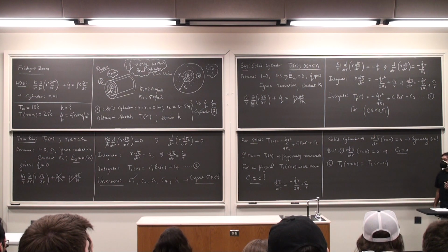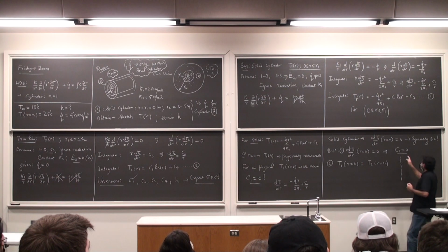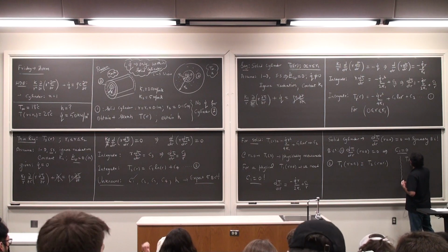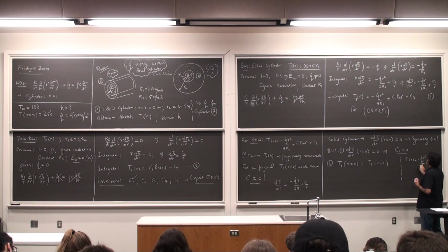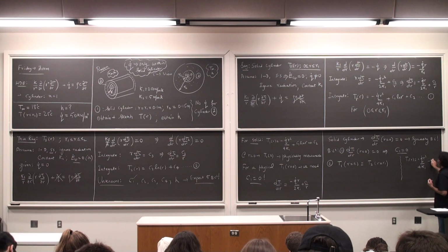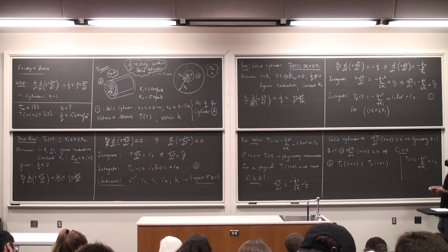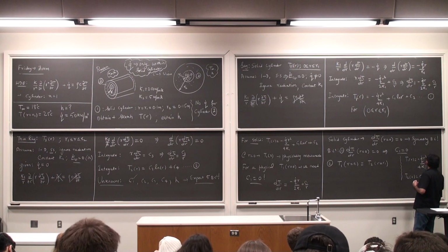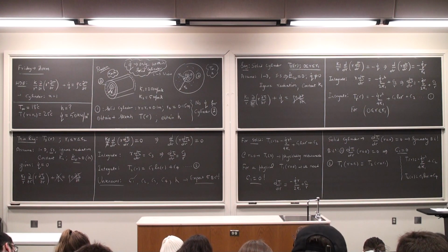Let's make use of this boundary condition. So first of all, based upon what we found out, C1 is 0, so T1 of R is minus Q dot R square by 4K1 plus C2. This is T1 of R. T2 of R is just whatever we just did some time back, C3 ln R plus C4. So I am making use of the second boundary condition.